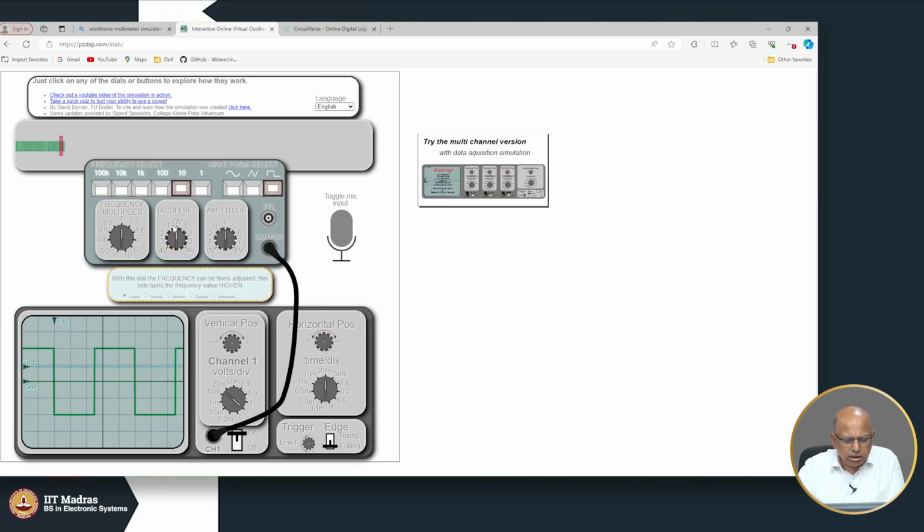You can measure, you can change, see this waveform, the DC value is 0. What it means is the average offset is 0. So, that is the DC offset. If you change it, then you can see that we added a small offset. As a result it shifted up. So, here we can change it, it keeps shifting up. Now I have added about 1 volt offset. So, now it has gone up.